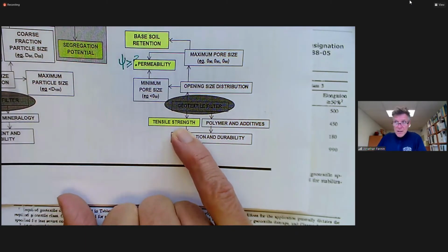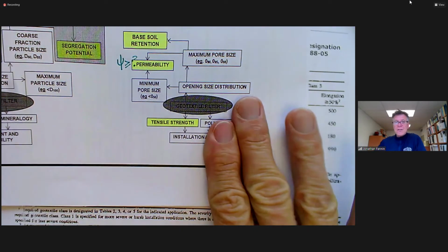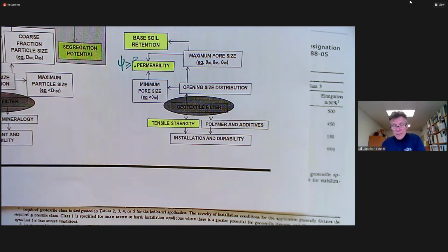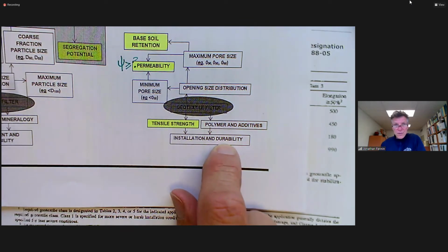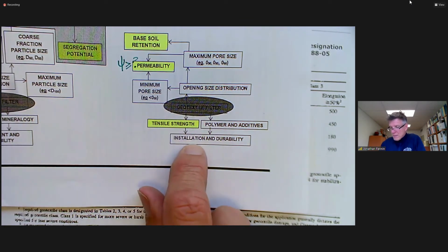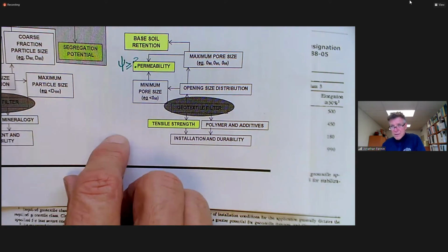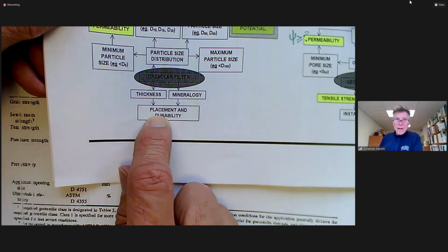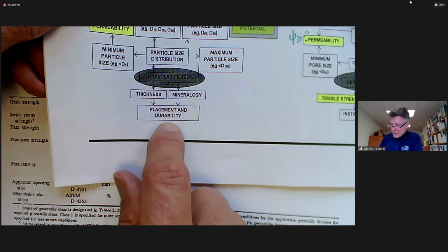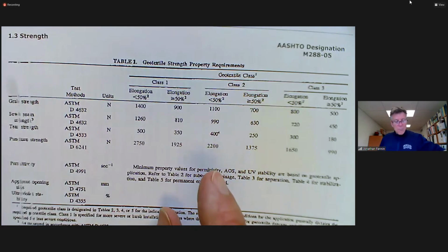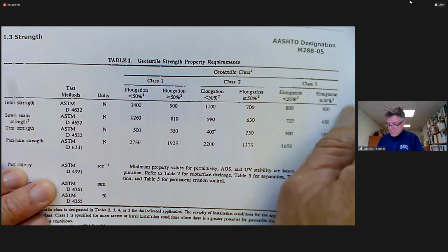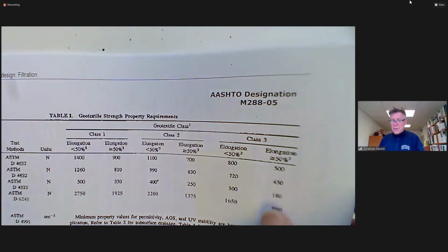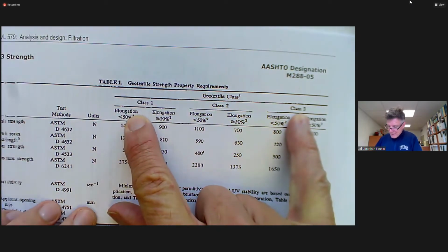We really want the geotextile to be strong enough to survive installation, and together with any polymer additives, for example for UV stabilization, to be durable over the service life of the structure. And this installation and avoiding punching holes in it and inadvertently damaging it, I'd say the analogy would be a little bit like the granular filter not suffering grain crushing and generating adverse fines. That would be my analogous comment. And pretty much everyone defaults in terms of adequate strength to the AASHTO. So this is really a highways approach, the AASHTO designation. You can choose one of 3 strength classes.